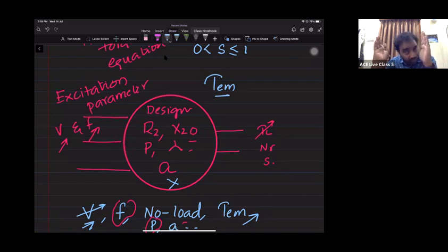If you are applying a voltage less than that, then the torque which is supposed to be developed will be less than that value, and the motor may not drive the loads. Why? Because you're applying a reduced voltage. So this is a very, very important thing. From that we can learn.